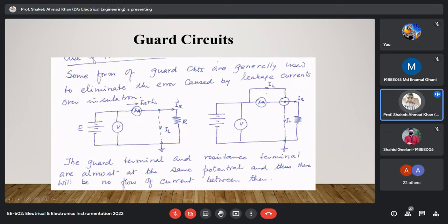It is flowing, it is actual conduction current, and it is flowing through the body of the high resistance, or insulation. So this indicates the conduction current which is flowing through the body of the insulation. And another thing I forgot to mention: leakage current is not constant, because it is flowing through the surface of the insulation.